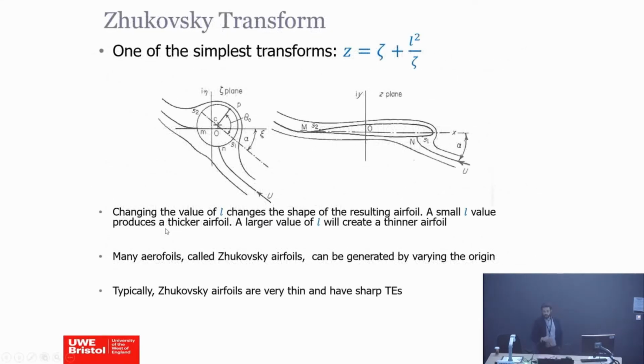So here is one famous transformation or mathematical trick. It's called the Joukowski transform. I don't want you to worry about that equation at all. Just understand there is something called the Joukowski transform, which allows us to do this mapping of solutions. It says that the link between the complex plane Z, which represents where the airfoil is, and another complex plane zeta, which represents the flow around the cylinder, is this: Z for the airfoil equals zeta plus some length L squared divided by zeta itself.